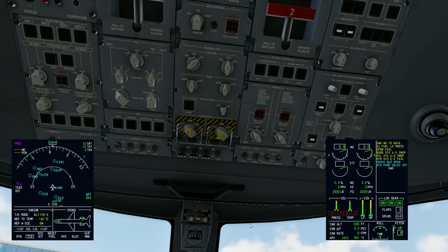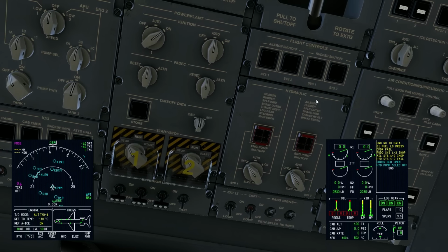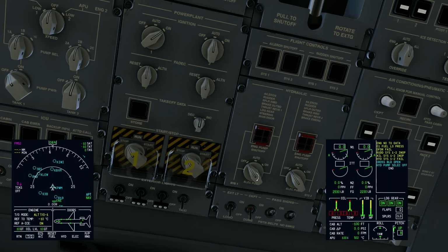Your ailerons and rudder, though, are hydraulically boosted. They are mechanically connected, so you can control this aircraft without any hydraulics. It is very, very difficult. We do it in the simulator, and it actually requires both pilots to roll the airplane, as in both of us have to use our strength to try to roll this airplane. It feels like the yoke's made out of concrete.